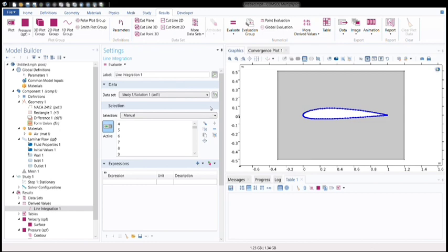We go to the expressions. We choose laminar flow as mentioned earlier, the auxiliary values, and from there we extract the stress component. The stress in x represents the drag force, and the stress in the y-axis represents the lift force.